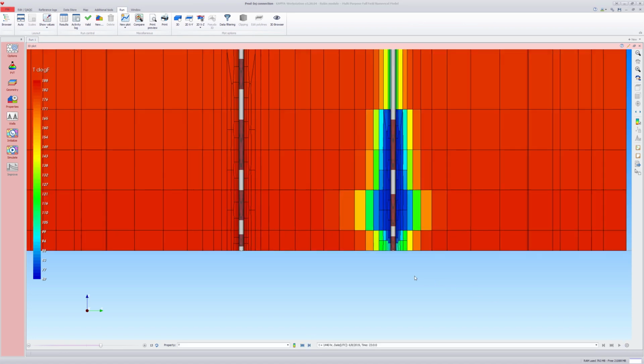The cold injection water starts to cool near the wellbore, and then progressively the reservoir cells between the injector and producer. However, by the end of the simulation, the thermal front is still far from reaching the producer. Hence, the saturation and thermal fronts do not propagate at the same speed, which is given by the permeability and thermal conductivity respectively.